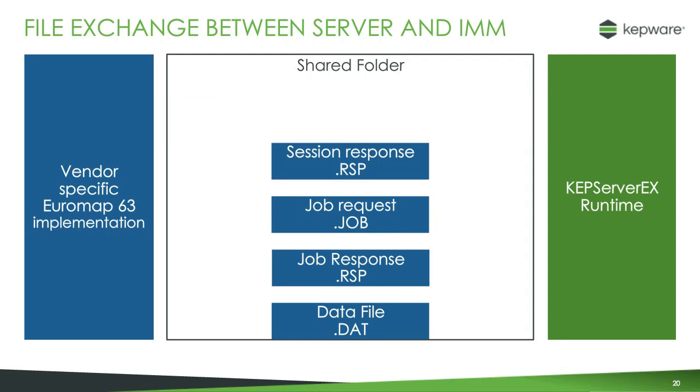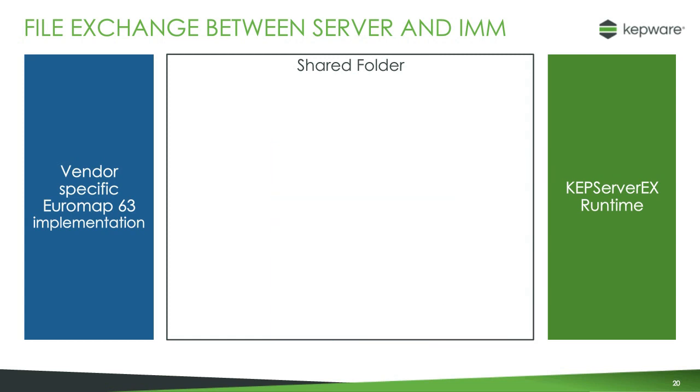That indicates to KEPServer that the machine is ready for us to read the information, so we go out and read the different responses. And after parsing that information and providing that into the tags within the server, we go and we clean up the files. So pretty straightforward as far as file transfer. What's really interesting and the really fun part of developing this driver has been the variances between the different vendors and the way that they implement it.